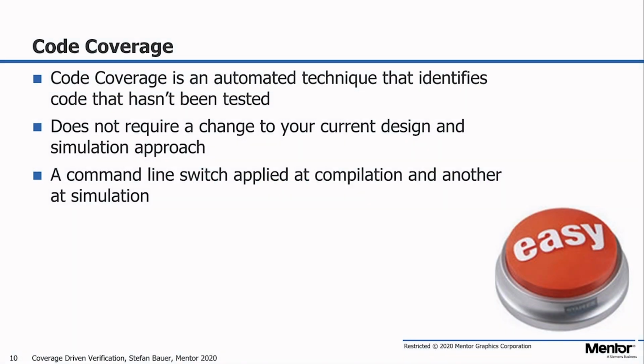Code coverage is an automatic technique that identifies code that hasn't been tested. It does not require a change in your current design or test bench or simulation approach. You simply need to add a command line switch to your compilation. You see here for vcom you need to add +cover, and you can define the different types of code coverage.